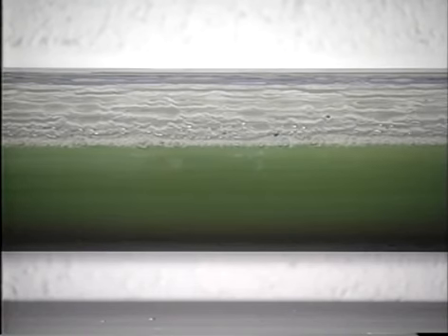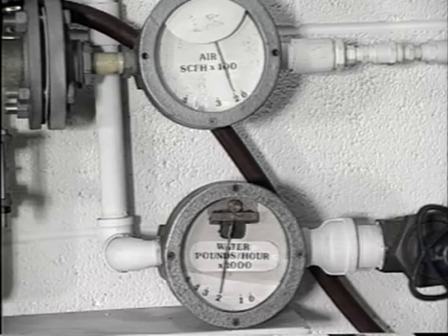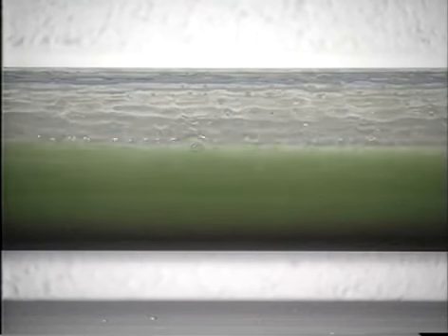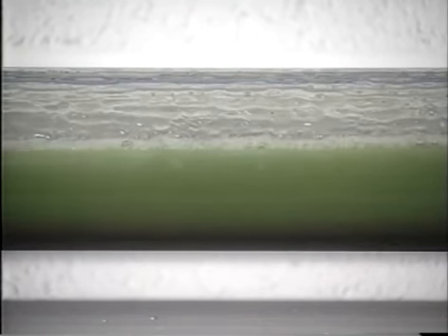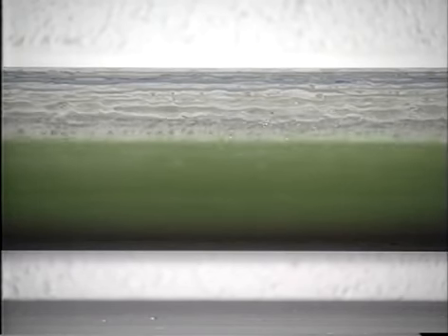water increases to 5/8. We now introduce compressed air into the system to simulate flash steam, with a flow rate of about 200 standard cubic feet per hour, and the depth of the water recedes. We are increasing the speed of the water flowing through the pipe by virtue of the velocity of the gas flowing across its surface. Observe now as the compressed airflow increases. The waves formed on the surface of the condensate become higher.